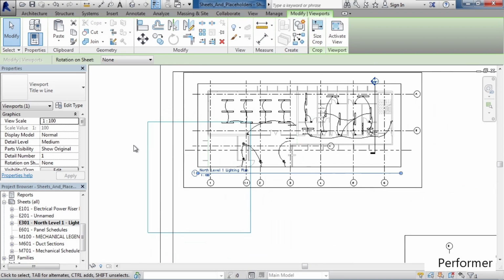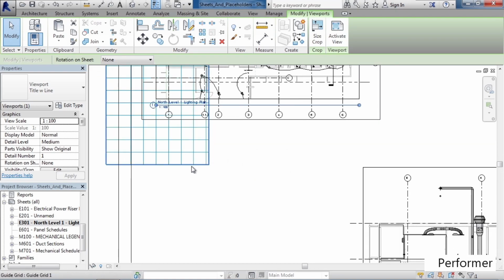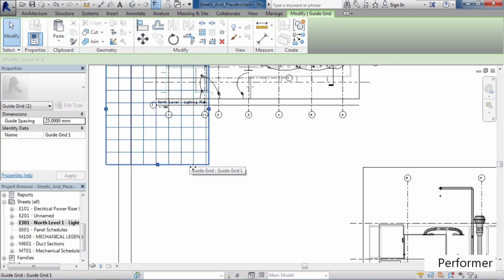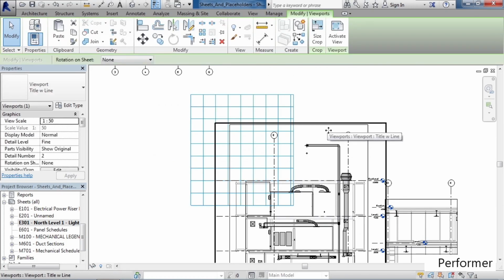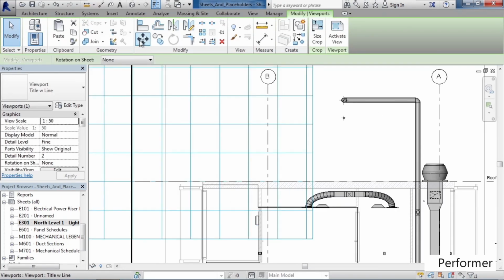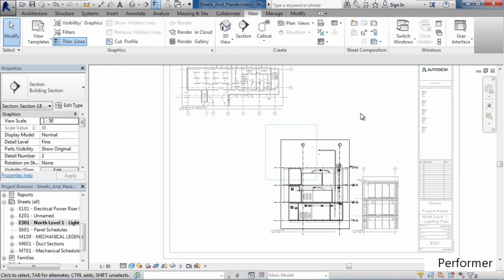And you would do the same thing to your additional sheet and the views on that sheet. Now if you wanted to move another view, simply mouse over the grid, select it, and then just drag this viewport window of the grid to the new location, and then repeat the process. Select the viewport, zoom in, choose the Move command, select an intersection of a grid or level line, and then move it to where you want it positioned on the actual blue grid, and then zoom back out.